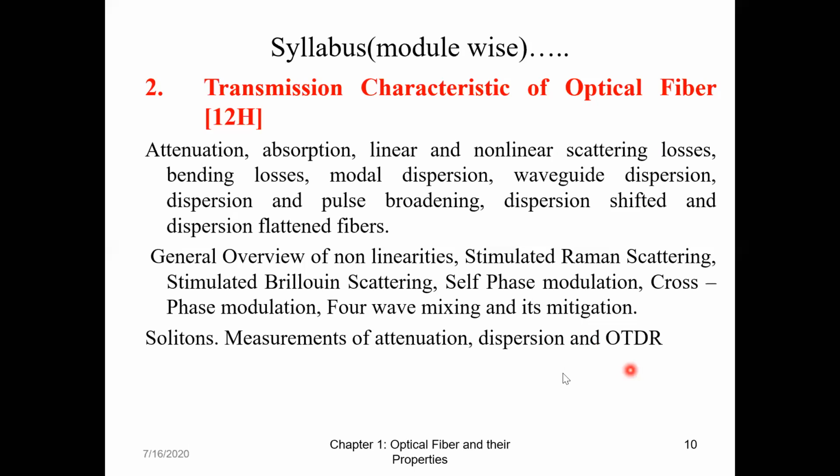So wherever there is a light cut, light reflects from that particular point. And we calculate the time, kitna time लगता है वो light reflect होने में. So that's why it is called an optical time domain reflectometer. Based on the time taken for the light to reflect from the cut, or from a bend.